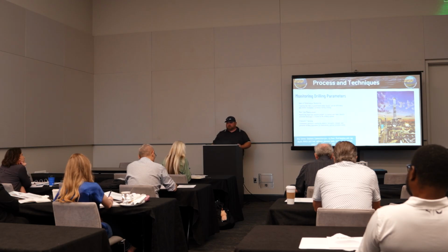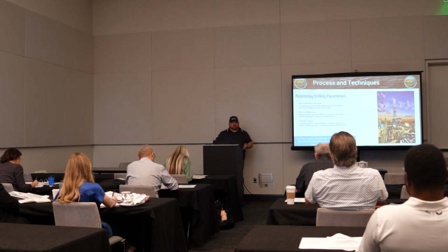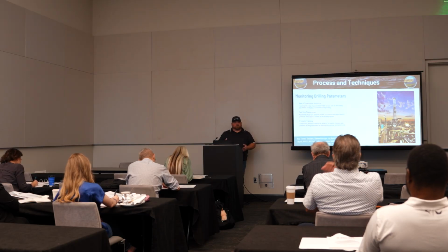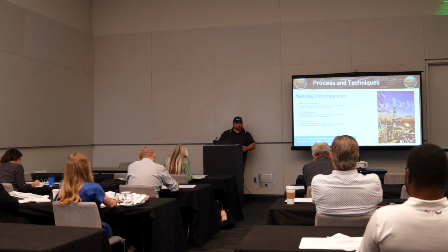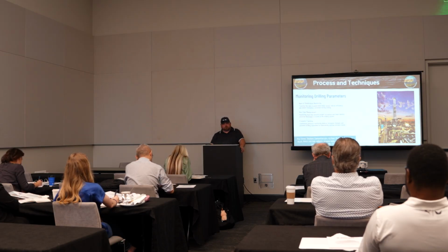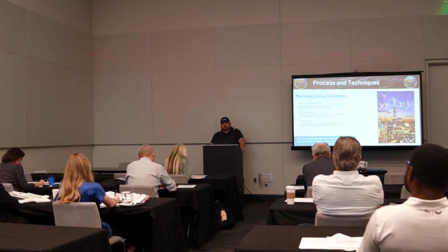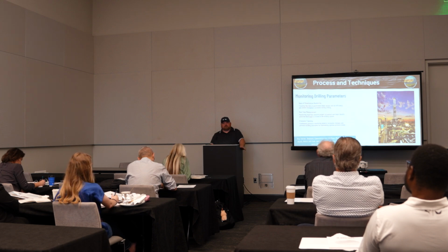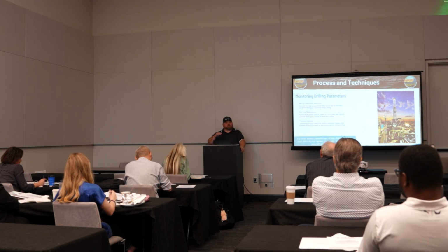Drowning your agitator will either cause you to suck mud into your polyflow line, blocking all gas readings, or it'll drown it enough that it can't break the gas out of the mud. Typically, depending on the drilling fluid, with OBM, oil-based mud, the agitator sits about 3 inches from the top of the mud, pretty much at all times going into the possum belly.